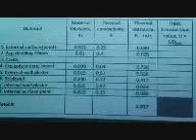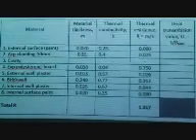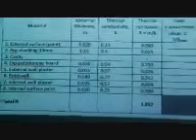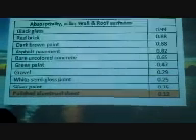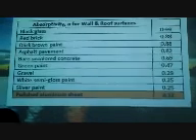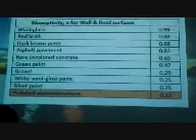To find U, 1 divided by R, and the value of U that we get is 0.76. This is the absorptivity alpha for wall and roof surface. For this one we choose polished aluminum sheet, and the value is 0.2.